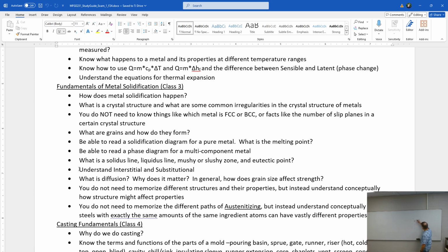And then when those two run into each other, they're not aligned with each other. And so the grain boundary is kind of crazy. They will have a bunch of errors and places that motion can happen near the grain boundary. Yes? What are the little sites called again? Nucleation. Yeah. So what you end up with is the city of Bellingham, right? The city of Bellingham started as 4 little communities, and when they grew together at each of the corners, the streets don't match. So then you get these weird mismatches that you have to figure out. So it's awesome that we live in a solidification.